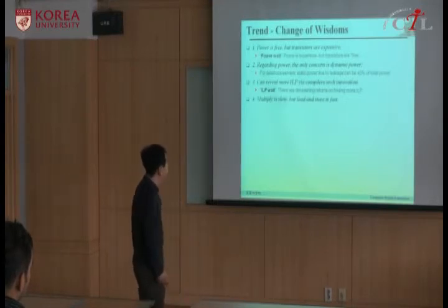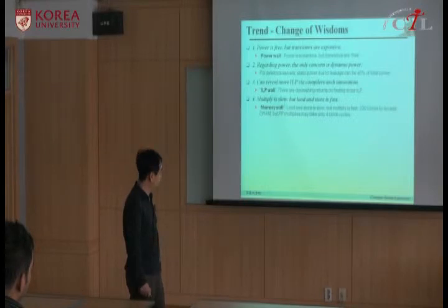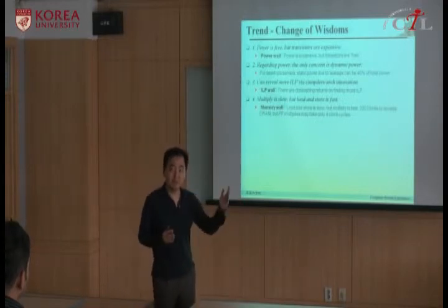And people think multiply will take long and load and store are fast, but we have the memory wall. Load and store are slow, and multiply is much faster compared to memory. It takes more than 200 clock cycles to access DRAM, but a floating point multiply takes only 4 clock cycles. So on-chip computation is nothing compared to off-chip memory.